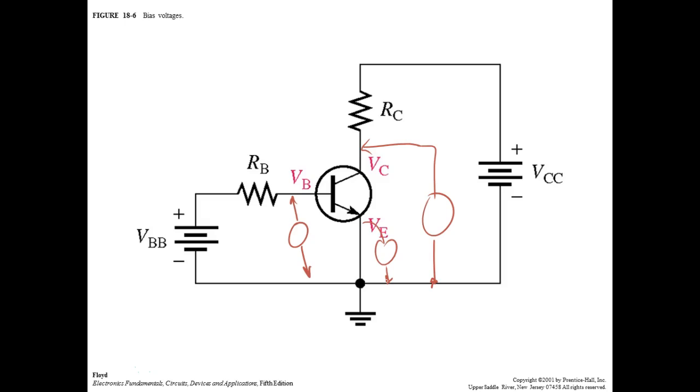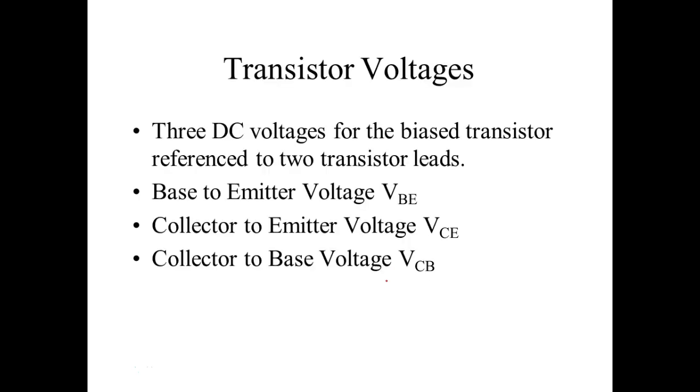Okay? Okay so far. Then we turn up with voltages that we measure between leads. And this is the common right here. So this is common. This is my meter common. So it's not circuit common, it's meter common. Y'all understand the difference now, right? So meter common is the black lead. And it's not circuit common because you can put that meter lead anywhere inside a circuit and it's not going to hurt anything as long as you don't touch them together.